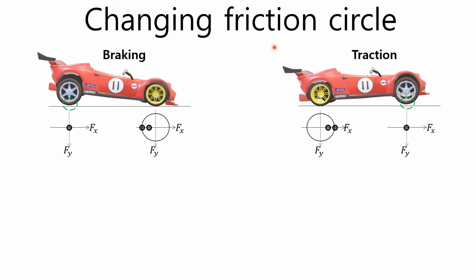During acceleration, when the front wheels reach the tilting acceleration point, the front wheels come off the ground and the front wheel friction circle becomes the friction point. On the other hand, all the weight is shifted to the rear wheel, which increases the friction circle of the rear wheel and increases traction friction force.